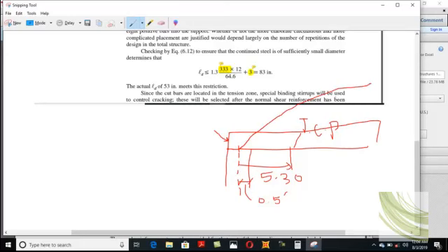Here is the start of the diagram. So you need to continue the bottom layer. This is your bottom layer steel. So this bottom layer steel should be continued for a distance of 3 inches. This length is basically 3 inches. Clear? This is 3 inches.